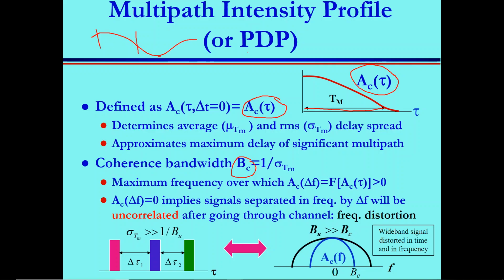Once you have a value like this, it becomes independent of this. This is not exactly random. The value here is very close to the value next to it. So these adjacent values are correlated with a high percentage. Now, for example, suppose this is the channel. You define the coherence bandwidth, the range of, let's say the x-axis is frequency, the range of frequency over which the channel seems correlated. So you will say this is the coherence bandwidth of the channel. The channel seems to be similar within this region.